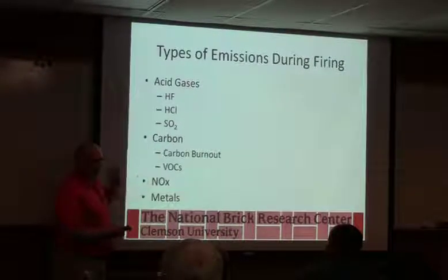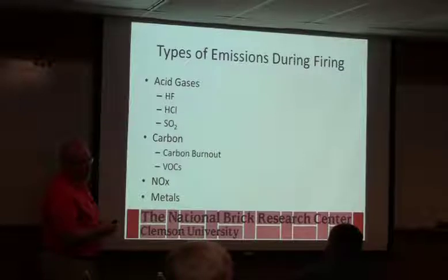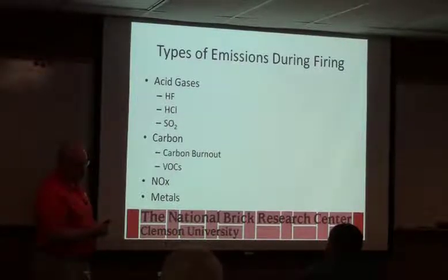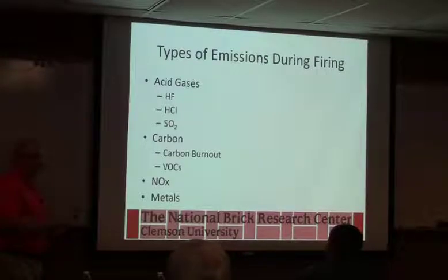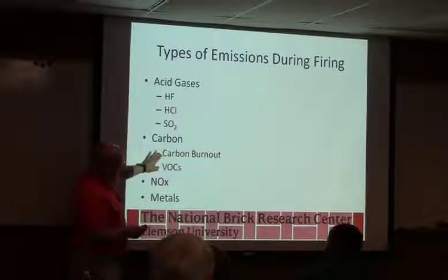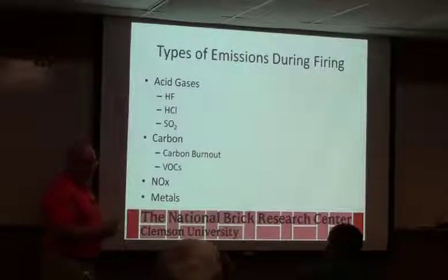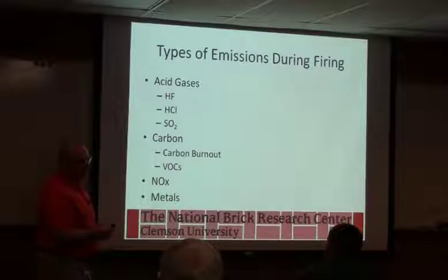Flashing in general is not really adding a whole lot as regards the major things we're looking for in emissions. We just mention it because sometimes it comes up. It's more of an opacity issue, because in your air permit there's probably an opacity clause. It has to do with whether you can see through the plume or not, and any kind of sooty emission would contribute to that. But as regards the hydrochloric acid, no, you're not adding to that. Basically all we're adding is soot on top, and we're not accelerating the creation of those others. That's coming from your raw material.